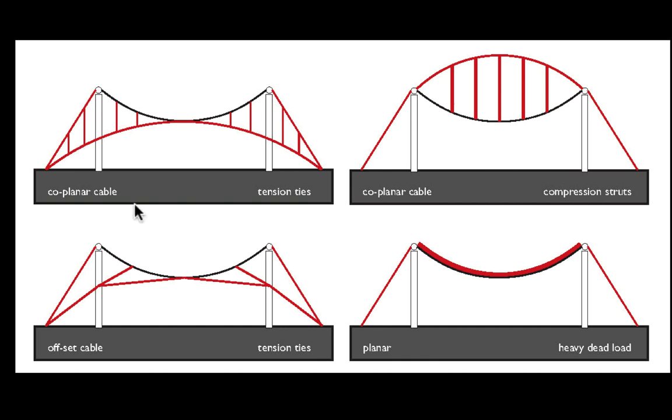We can also do this with cable ties, or we can calculate or even engineer the dead weight of the roof so that we can be assured that no foreseeable wind is going to provide enough uplift to actually pull the roof up. This is called a dead load strategy. And if we're building a roof out of, say, concrete, it's a perfectly effective way to do it.